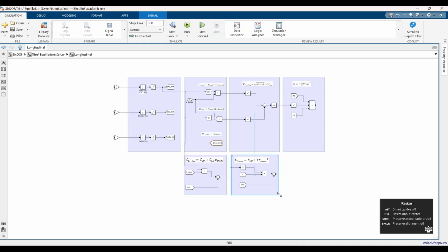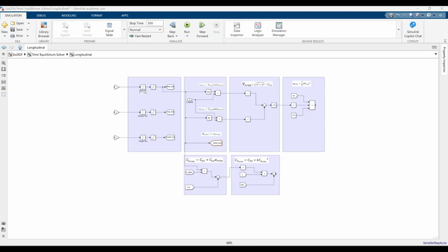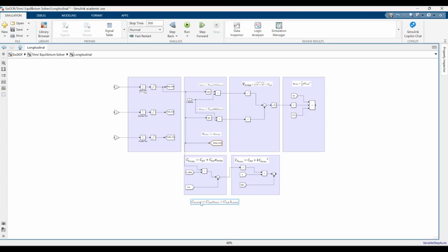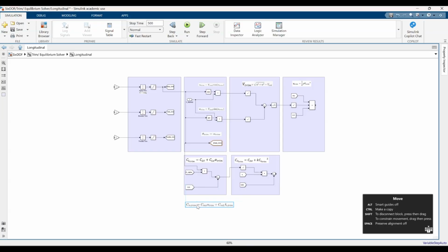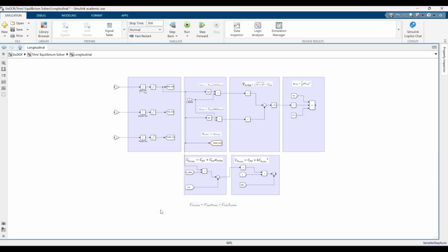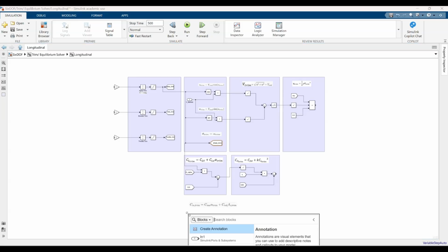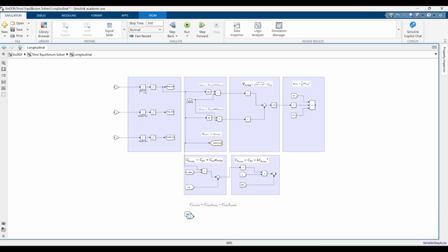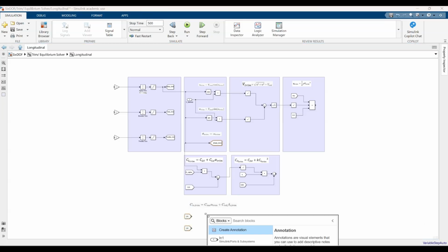Perfect. Okay, now another thing which we can get in parallel to all these is our CM trim term. If you remember, this is going to help us get our pitch moment M. This is the pitch moment coefficient. Now here CM alpha and CM del E are some of the things we can capture using a From block because those are already defined, right? So we will go into our moment subsystem to get them in a second.